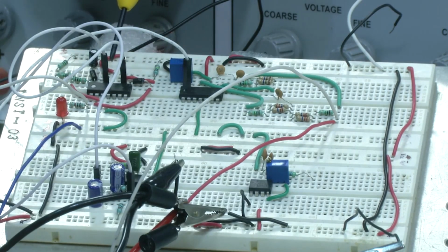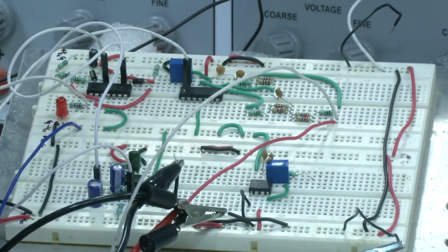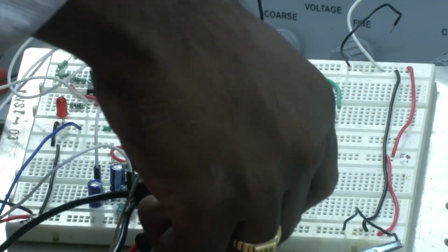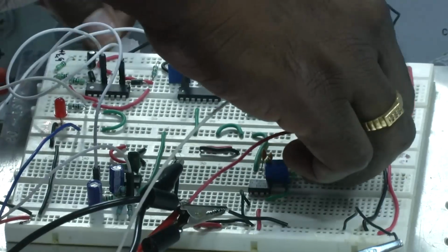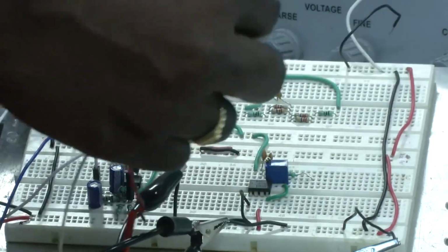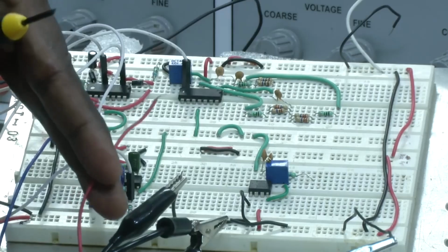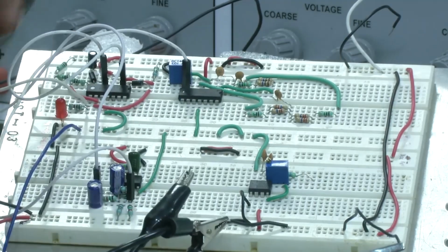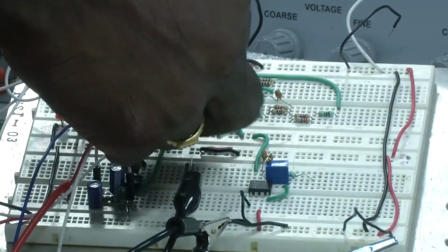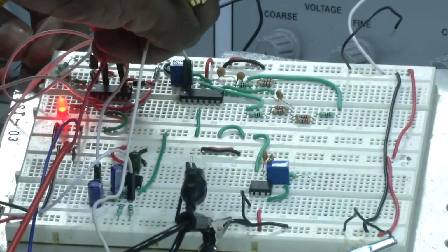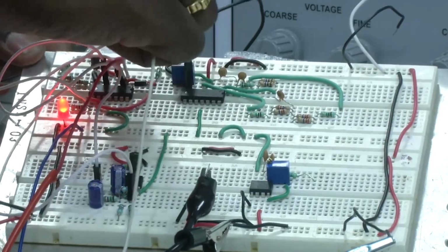This is the diode and the first quadrant portion of the op amp, which is the half wave rectifier portion. In order to verify that circuit, the input signal we will connect to the input of the operational amplifier, that is at pin number 3. I will take the input sinusoidal signal of 3 volts to the third pin. The third pin is somewhere here, and this is the output.